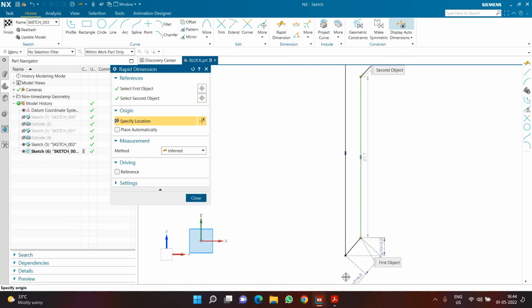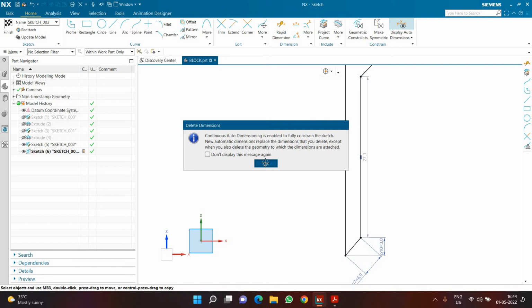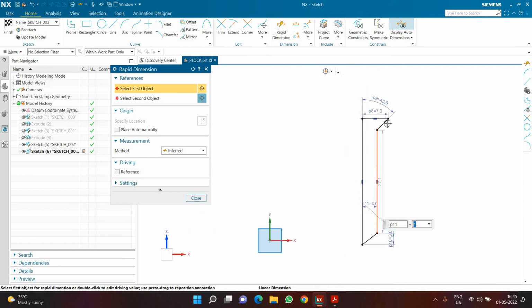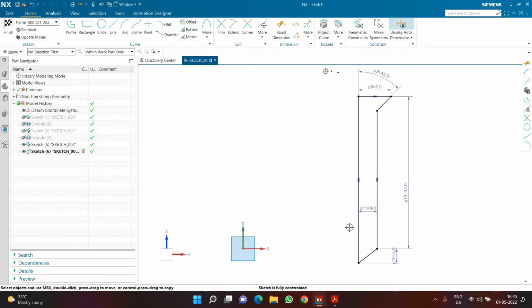And then what I want over here is not this align dimension as 4. I'll create a distance dimension as 4 like this, and then a total distance till here as 32. So this is what you need to create a sketch of. As you can see clearly, this is what I have created using the sketch feature itself. Now I'm going to click on finish.